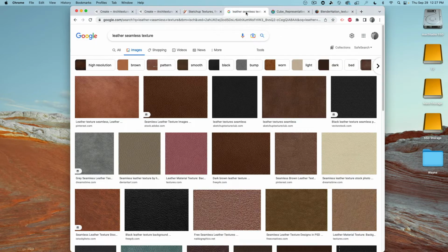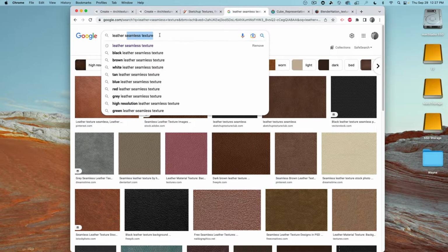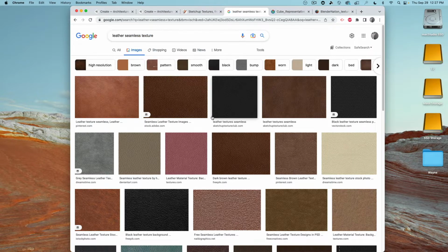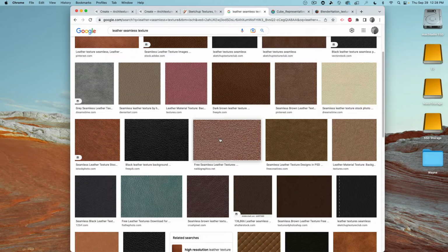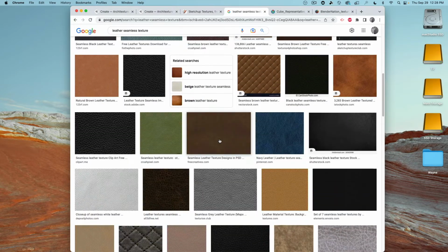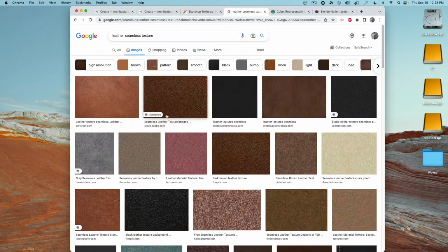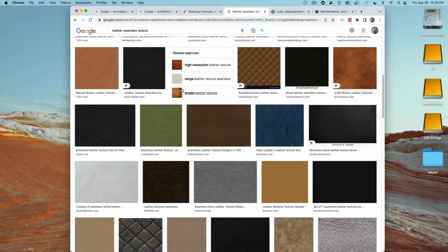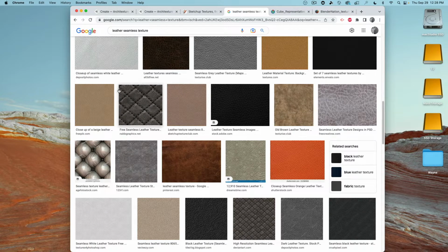to use. We can also look for materials in Google, and then always we type in the type of material and then "seamless texture", because we want to have images that can be tiled, so we don't really see the seams or how something is tiled, because then it becomes very obvious. It's kind of like one irregular piece we glued next to each other. And you see all these images, which I'm searching here under leather seamless texture, they look very even. Like this can connect here.